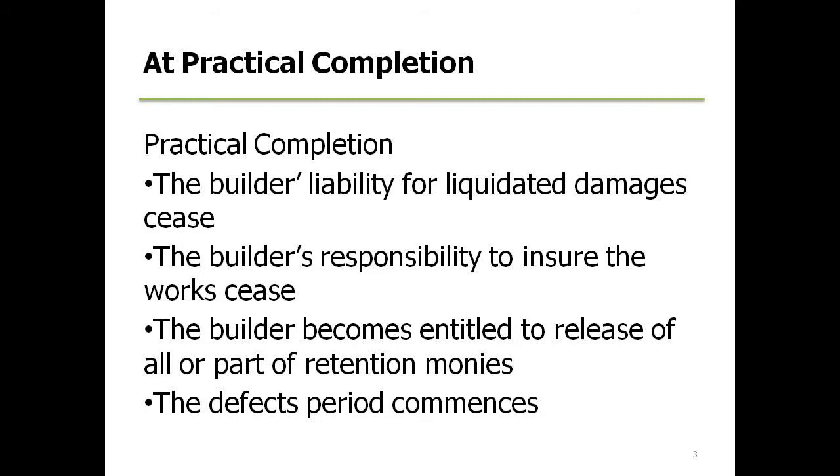It's that 12-month period between practical and final completion, where the building goes through a full year. That ensures that all the services and the building respond to the 4 seasons of the year. The mechanical equipment, the air conditioning equipment, can be tweaked. All those issues can be further fleshed out, where there's likely to be problems because they weren't built correctly or maybe the design wasn't fully considered for occupancy. So that 12-month period is really important.